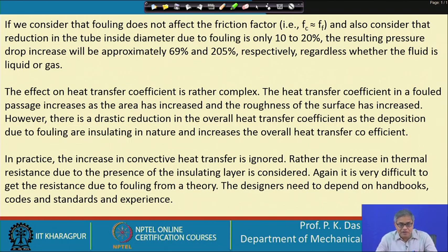The effect on heat transfer coefficient is rather complex. So, we have seen only the effect on pressure drop, from which we can determine the pumping power. The effect on heat transfer is rather interesting. The fouling deposition will reduce the passage.